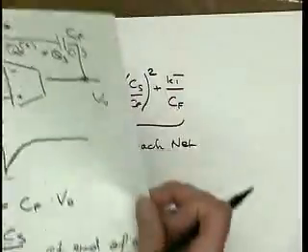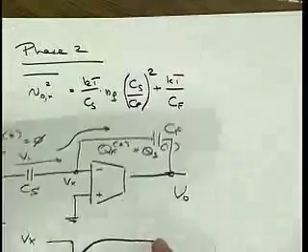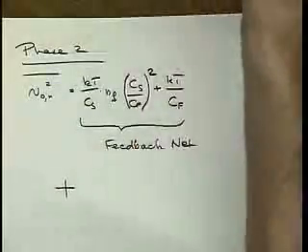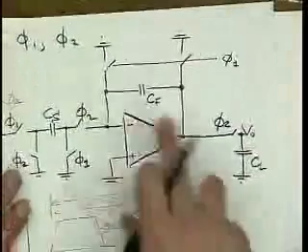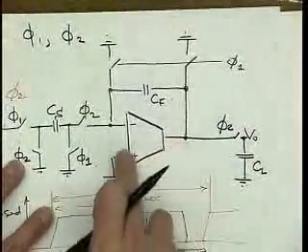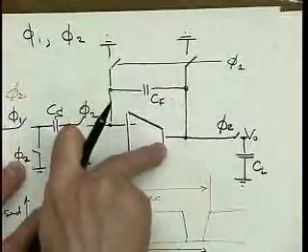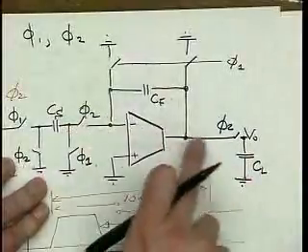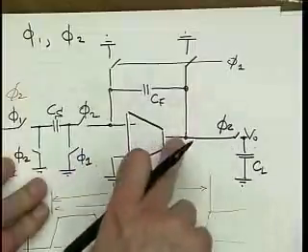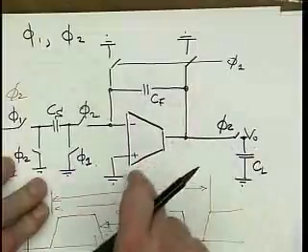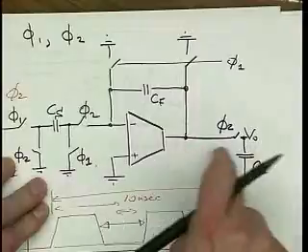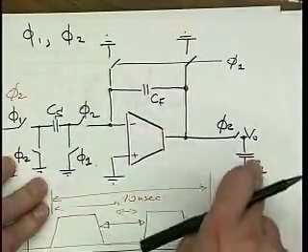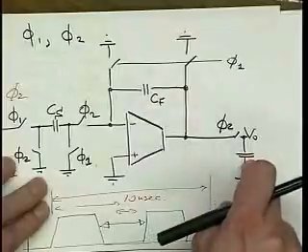So during phase 2, the amplifier also generates a signal and charges CL to the signal, but it also puts out its own noise that, together with its output impedance and the switch resistance and CL, is low-pass filtered and produces a noise voltage on CL here.